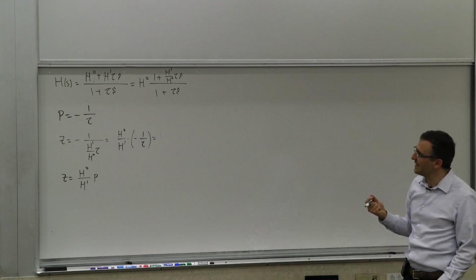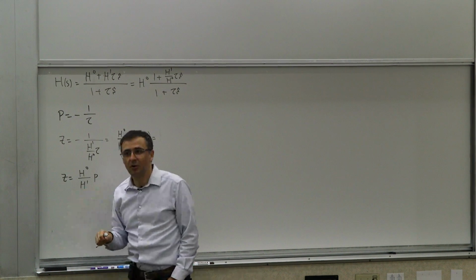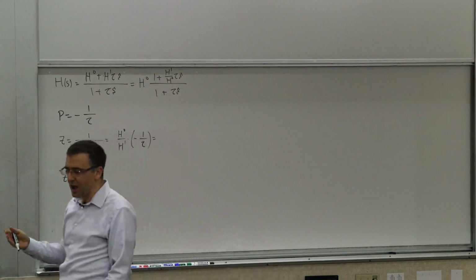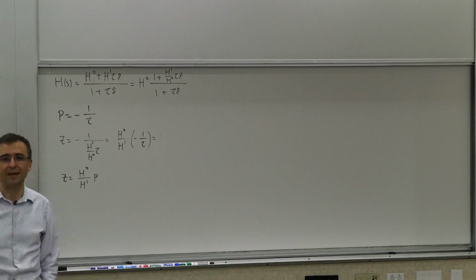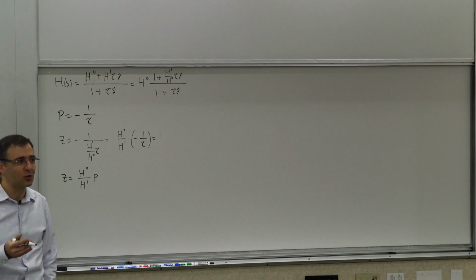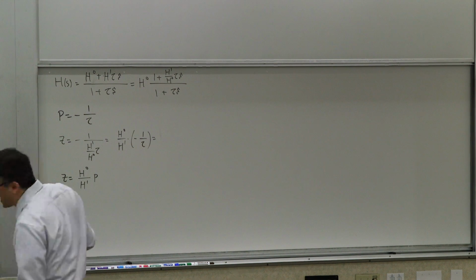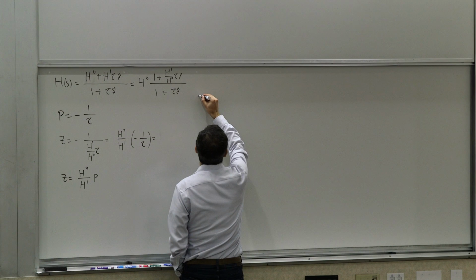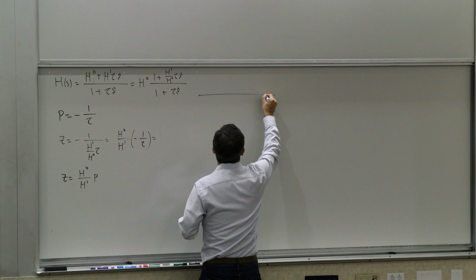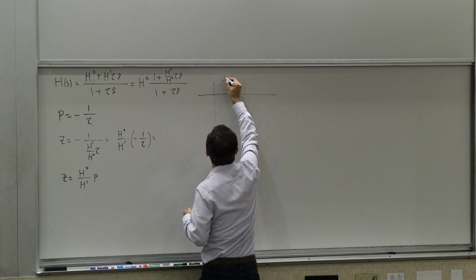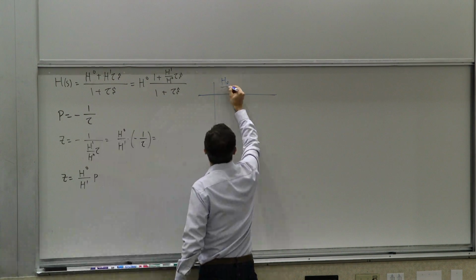By looking at the ratio of h1 and h0, you can tell where the zero is with respect to the pole. And this is quite useful because by evaluating this ratio, both in terms of magnitude and sign, you can decide what kind of transfer function a system should have without writing the full transfer function or doing the complete analysis. All you need to know is these two transfer constants, and then you can tell. In particular, we can even make a little table here.